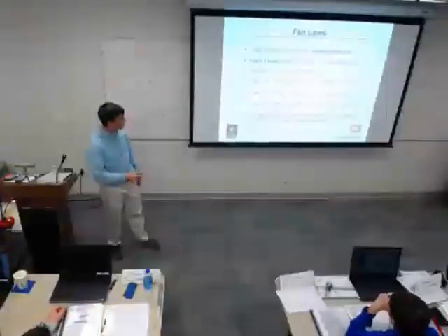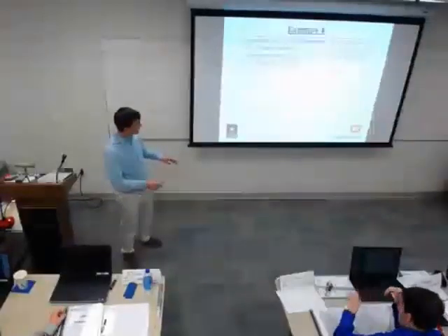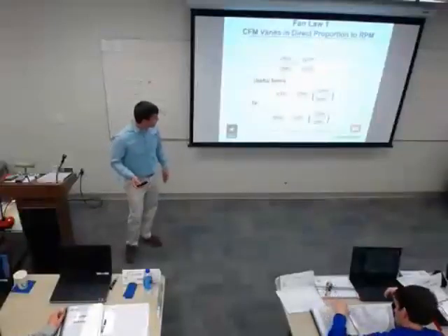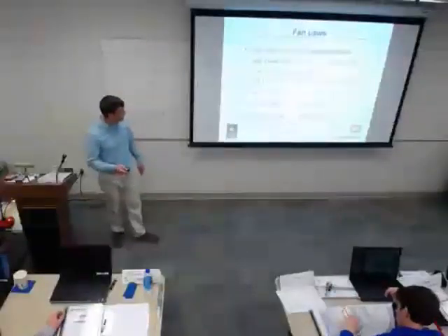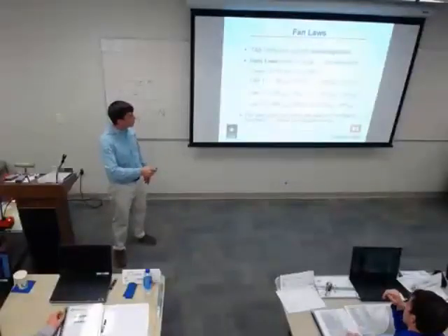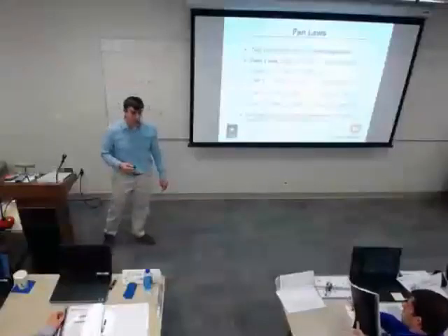I'm going to show these in a little better format in just a second, because to me they make more sense in that format. But just to summarize them, there's a direct relationship between my flow rate, my CFM, and my fan RPM.